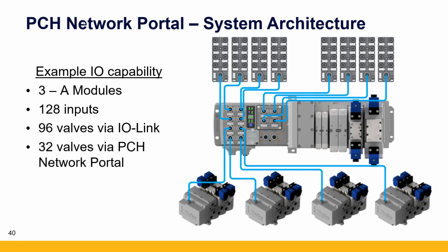But what I'm going to do here is simulate a power dip. So look at the bottom left here. Now that aux power just dipped to 19 volts, so it's giving you a red status light. You'd see that on the device. It's telling you, hey, you have low voltage. Now it went back up.